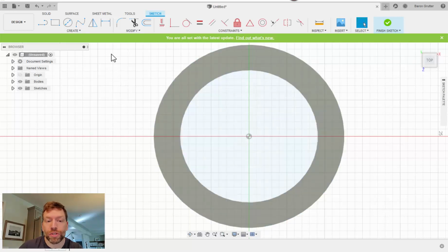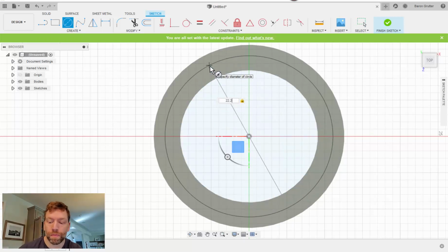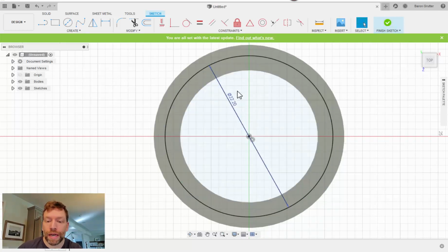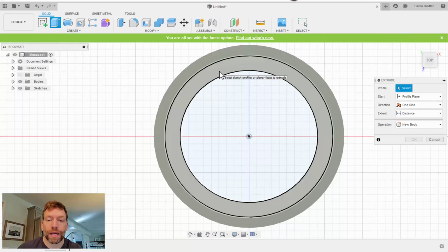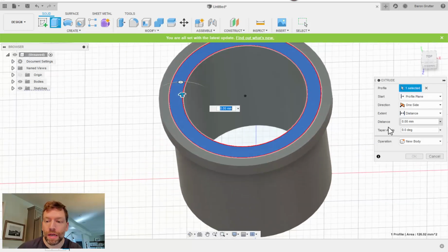I could just extrude these too, but instead what I'm going to do is create another circle that is that same outside diameter, which was 22.2. Done. I could redraw the inside one, 18.2, but as you'll see, I can go ahead and click it anyway because it assumes that line might be relevant. And so now I knew the distance I wanted here.